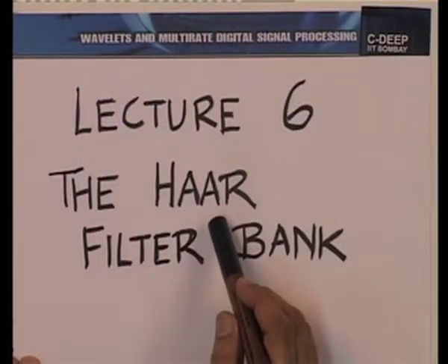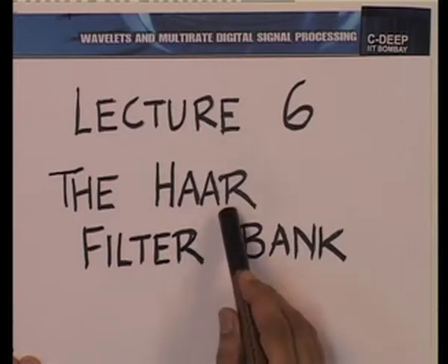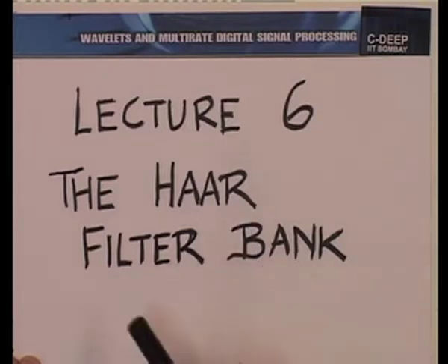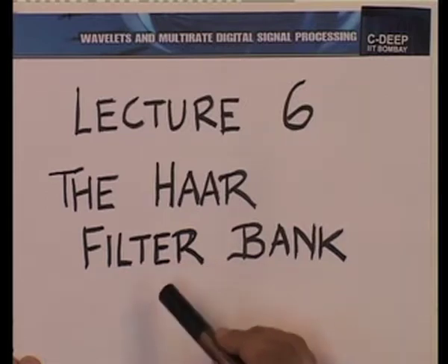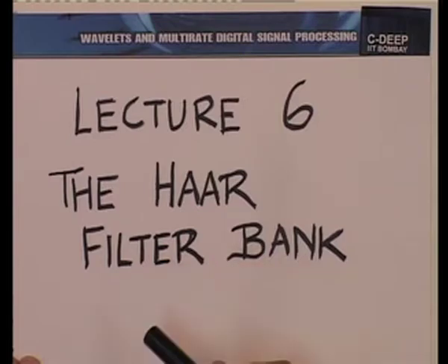In this lecture, we continue to build on the idea of connecting multi-resolution analysis and a set of filters. And therefore, we shall call this lecture a lecture based on the Haar filter bank. Haar, if you recall, is the multi-resolution analysis that we are discussing, and we have talked about filter banks earlier, a collection of filters with certain mutual and individual characteristics, either with a common input or a common point of output summation. So, we are going to build up the connection between the Haar multi-resolution analysis and filter banks as we understand them in the discrete domain.